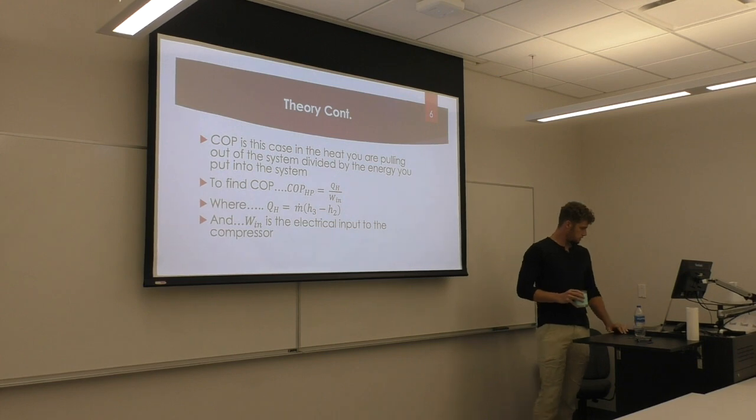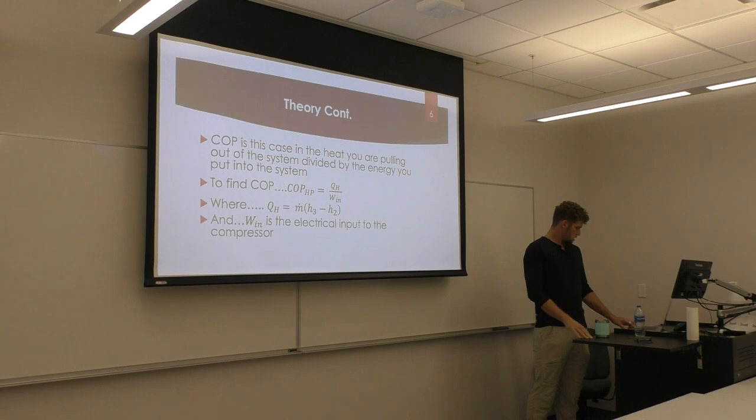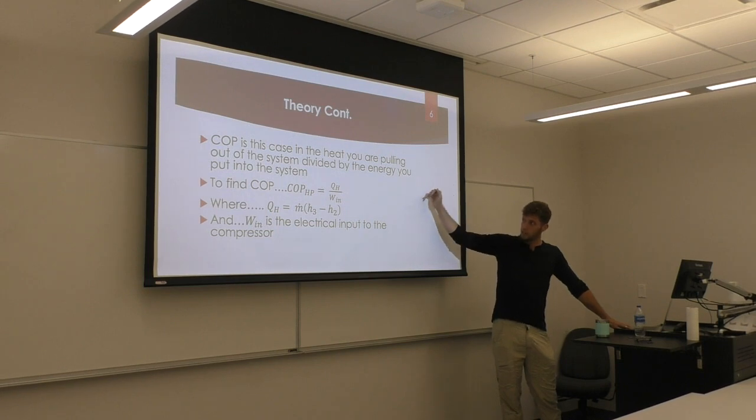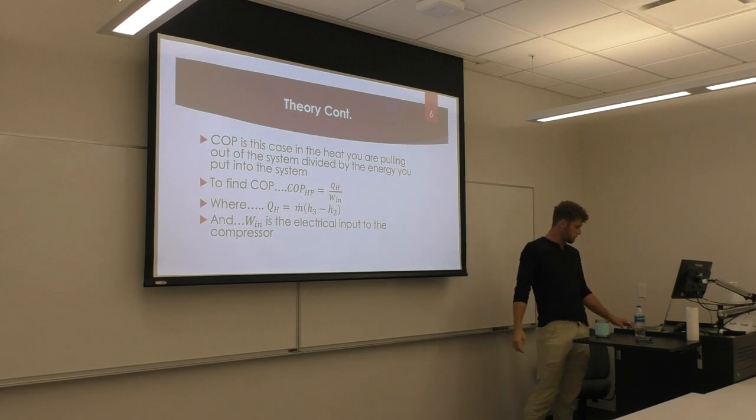Some more equations. This is how you find the COP using heat transfer and work input. This specific equation right here would be for your compressor. You use the heat coming off the condenser and then the power going into the compressor, electrical, and that'll tell you your coefficient of performance, or how well you're doing, the input to output of the system.